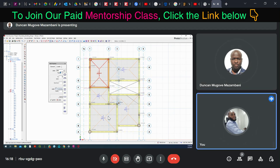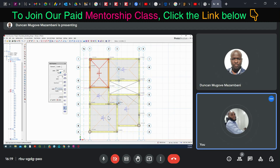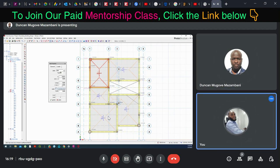Type 12. So choose that. Now you can see that you have other places to put values. You can see L cant. L cant means length of cantilever. Our first length here is 900, right? So put in that place 900 for our cantilever length.